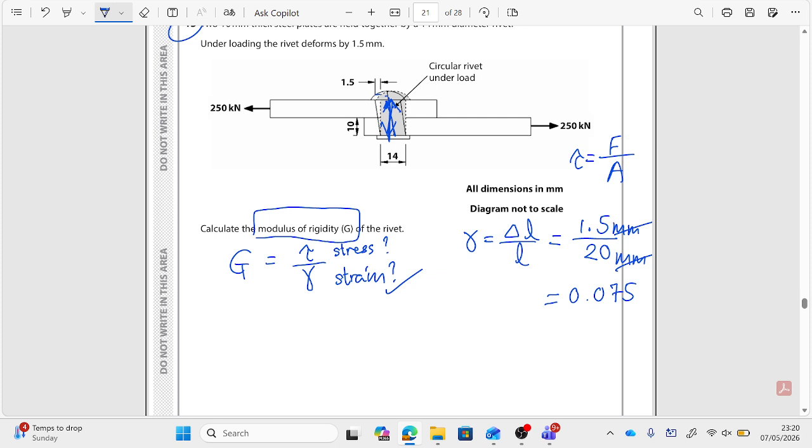Just so that you know, if I was to pull this bar to the left, this can't possibly do that if I don't fix this part onto some sort of rigid position. If you don't mount this part somewhere, all it will do is pull the whole thing to the left-hand side, isn't it? Think about that.